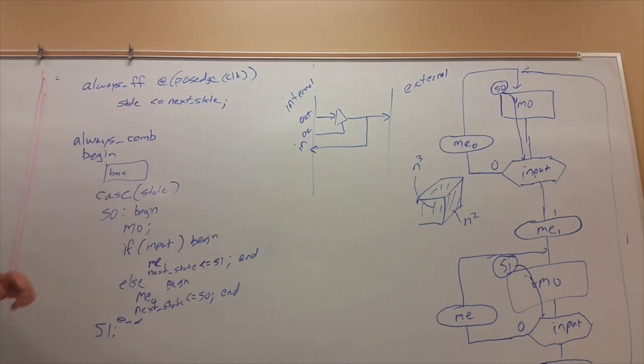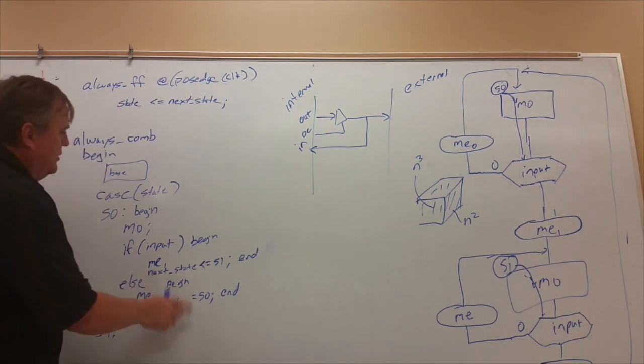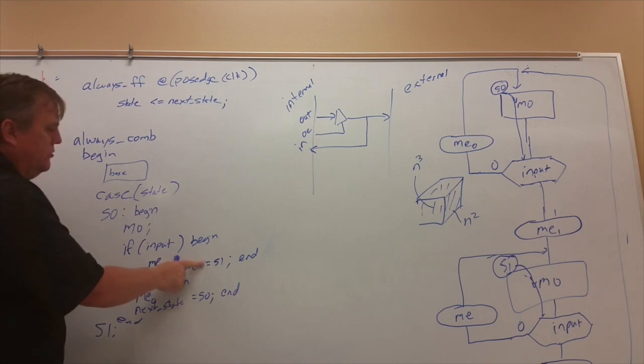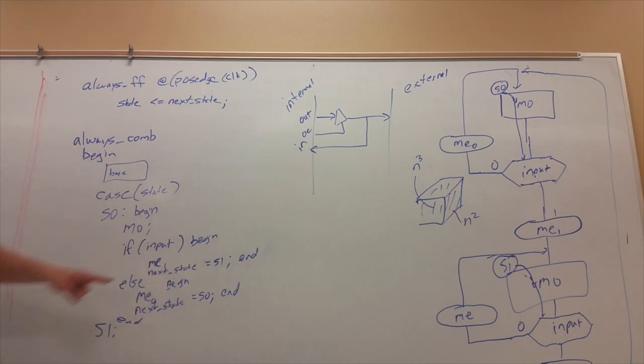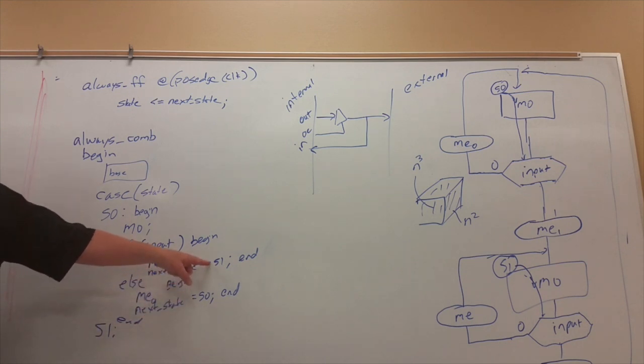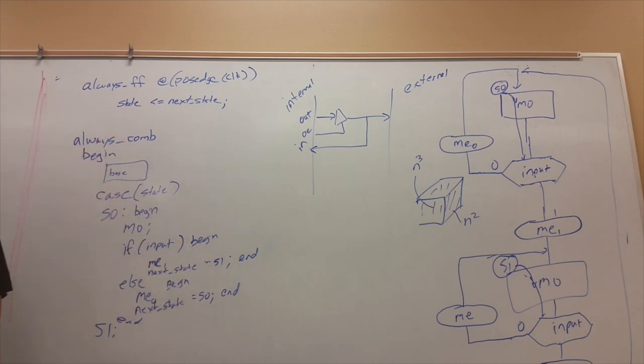And actually I should have done these. Everybody should have flagged me on that. That should be a straight one. We want the instantaneous, i.e. the blocking assignments, there and there. Because remember, we want blocking assignments inside the columns.